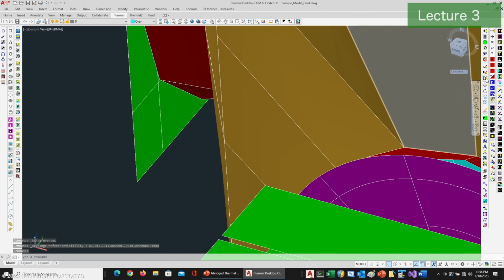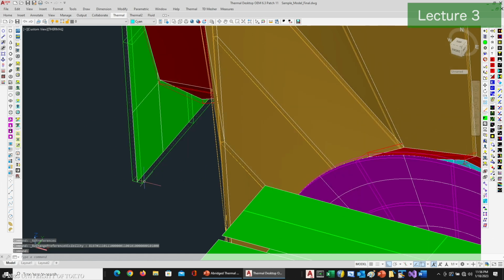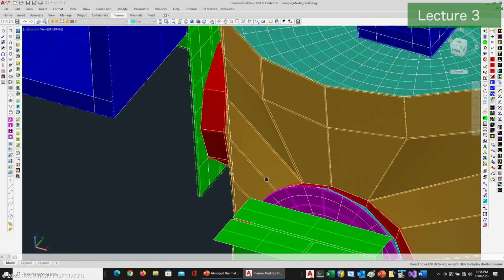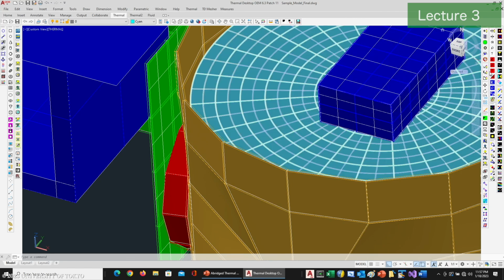So what that's very useful for is when you're trying to compare it to the CAD. Now I can see, does my CAD roughly fall within this envelope? So this is a good way to see, oh, did I forget to change the thickness from the 1 meter default? And I get this huge area there. So this is a good way to check and see whether my 2D models, expanded in the thickness directions, line up with my CAD, which is generally thin-shelled elements or thin-shelled surfaces. So that's another good check to do.